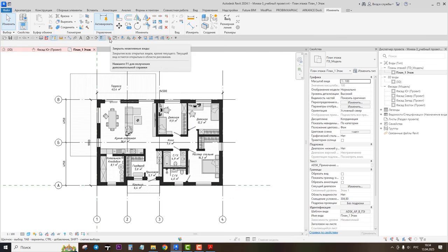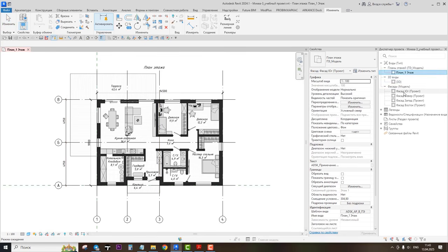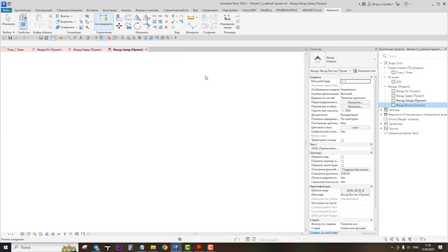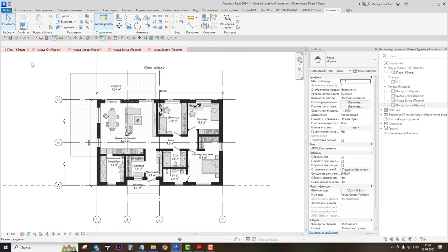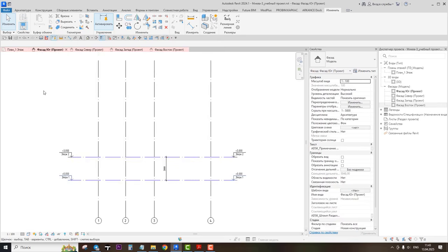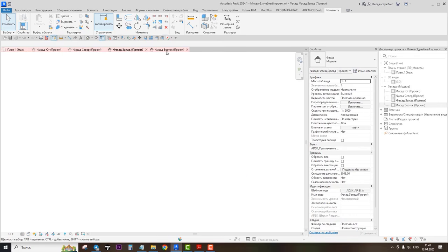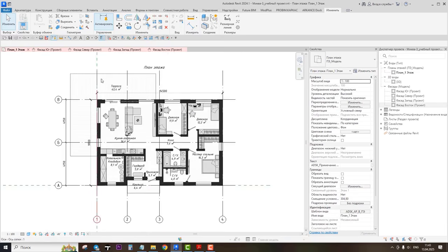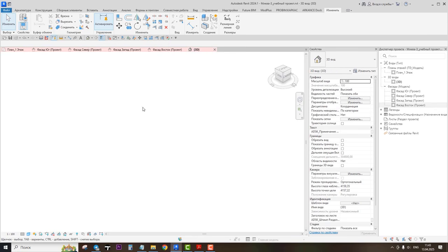Close all inactive views. There is a special icon here. This icon. One more thing about the interface. If you have a lot of windows open here, for example, a lot of views are open, you can change between the windows. Well, this house icon will get you to the 3D view by default. It's always in the project browser with braces. You can't rename, you can't delete this view. There is nothing here yet, of course, because we haven't created anything yet.